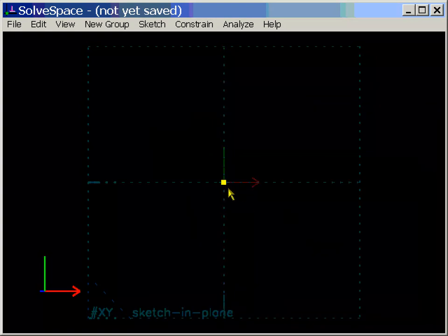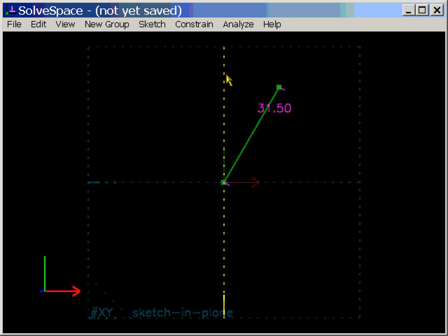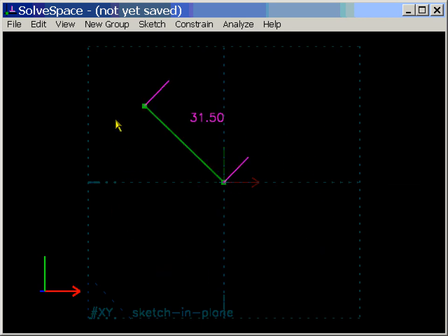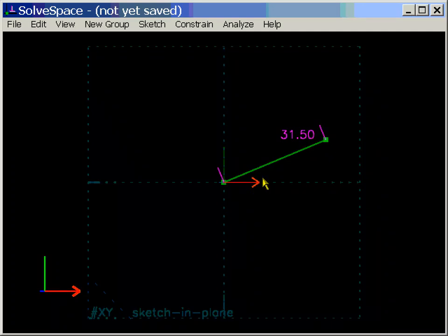Instead, we may want to actuate the linkage by stepping a dimension. So I'll draw a trivial linkage here. This line segment has constant length, so as we drag it, it sweeps out a circle. To constrain it, I'll further say that the angle between this coordinate axis and the link is fixed. I'll put it at 10 degrees.